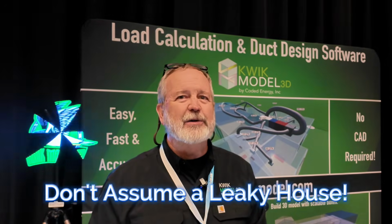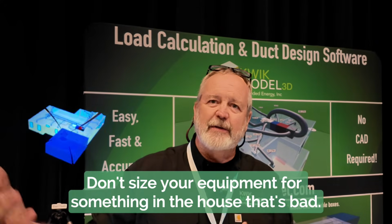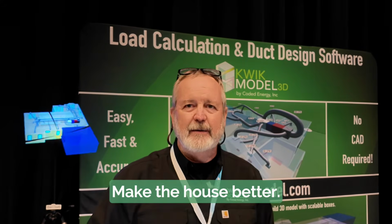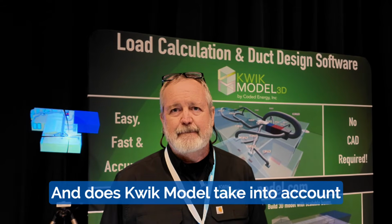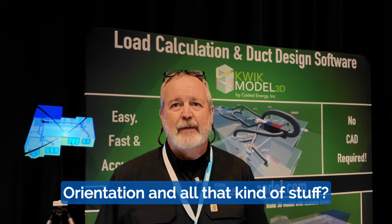I tell people don't do a load calc assuming the house is really leaky. That's really stupid. Don't size your equipment for something in the house that's bad. Make the house better. And does Kwik Model take into account, if I give you a blower door number? Absolutely, we can plug that right in, yeah. Awesome. Orientation and all that kind of stuff.